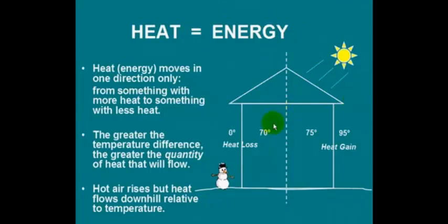Sure, it's better if you can supply heat low because it penetrates the room a little better. It's better if you supply cooling from overhead because you know the cold air is going to drop and the hot air is going to rise and all that good stuff. But is it absolutely essential? No, it's not. You can do it either way you want to.